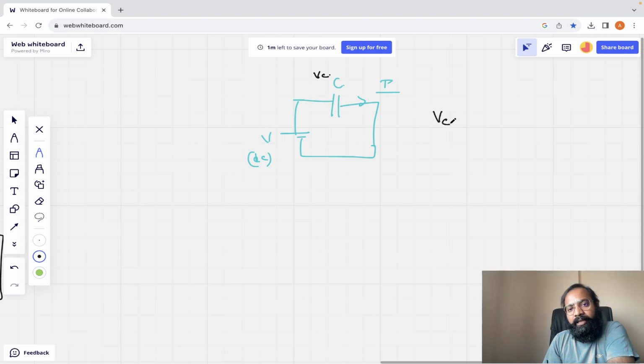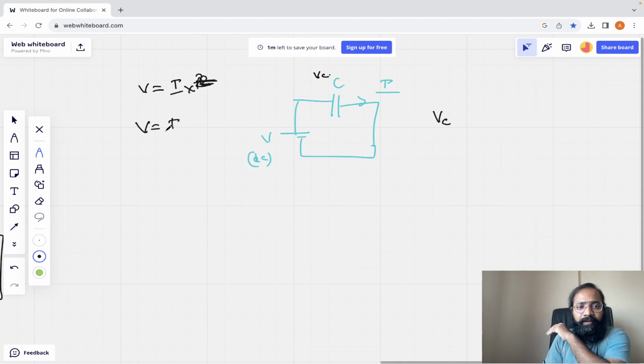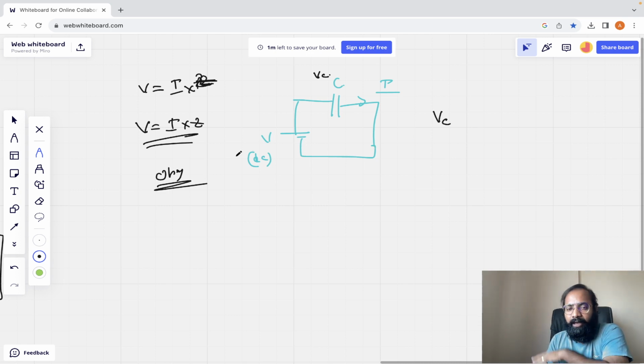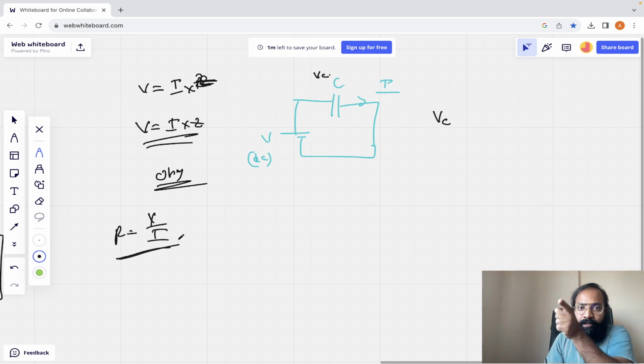Now usually, as per the Ohm's law, the voltage across any one device, or else the voltage drop across any one device, is nothing but the amount of current flowing through that device multiplied with the impedance of the device, that is V is equal to I into Z. It is what? The Ohm's law, correct? Actually it is the Ohm's derived law. What's the Ohm's law is that R is equal to V by I.